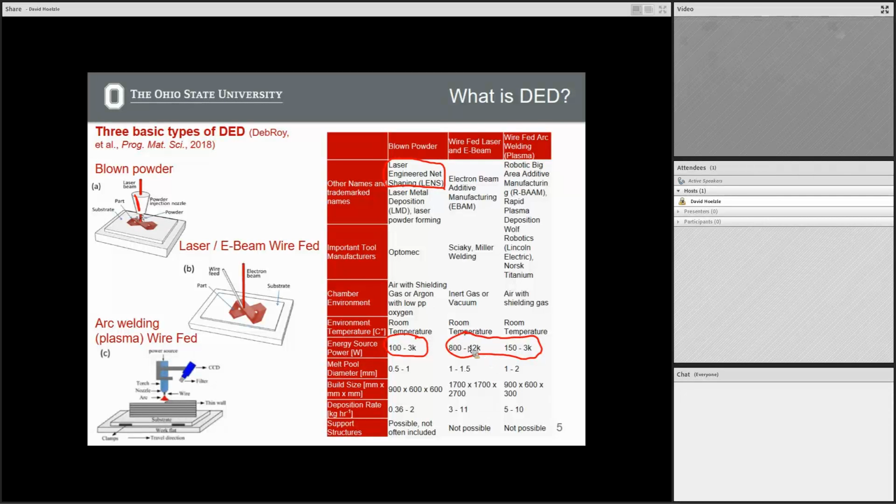So it's a higher energy level, and the reason is that everything you're doing here has a larger melt pool diameter. The wire that's being fed in is fairly large in diameter. It's tough to make wire that's mechanically sound and considerably small. You can't make a 30 micron wire and have it be able to be fed into the system.